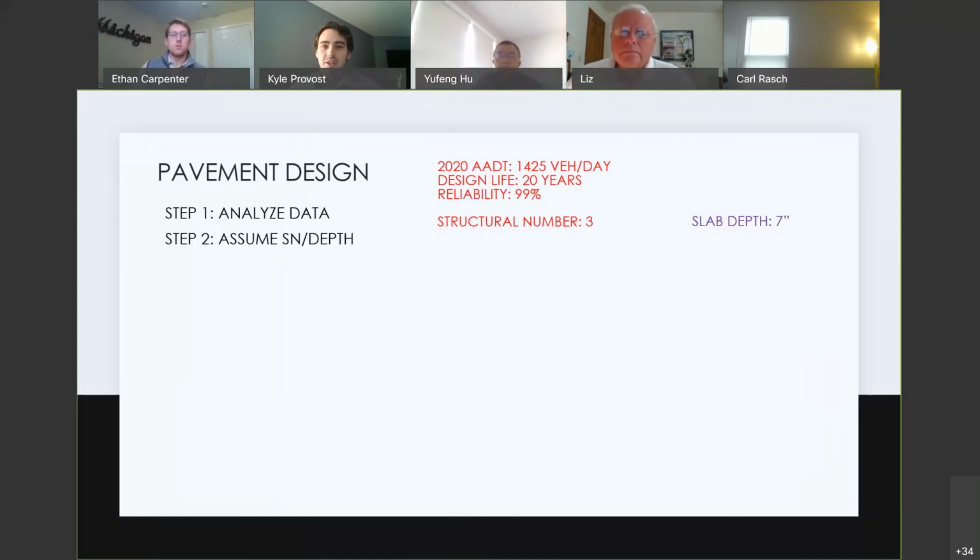After re-examination, we have determined that our proposed typical section be an HMA depth of 6.5 inches, an ag base of 6 inches, and a subbase of 18 inches. This is our proposed typical normal section with a 2% crown.